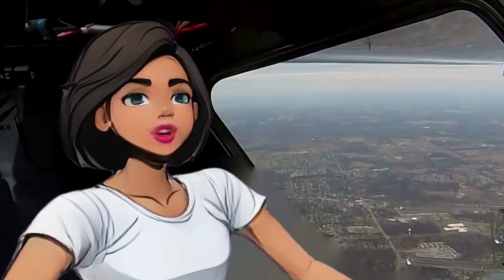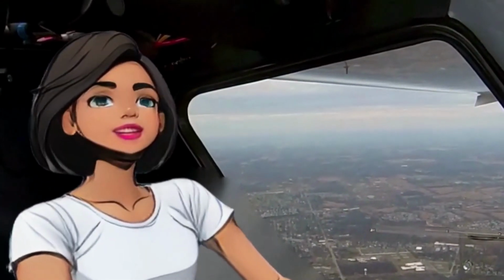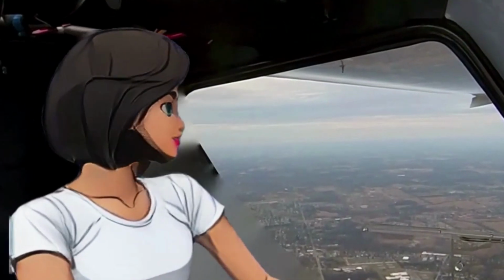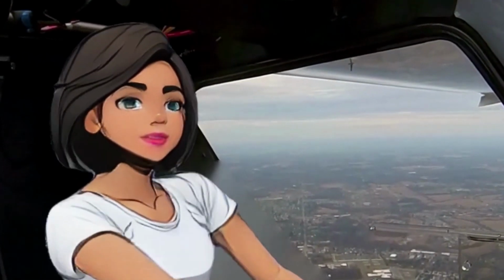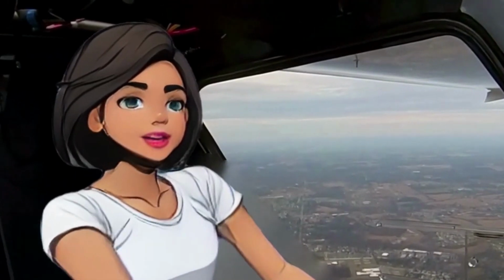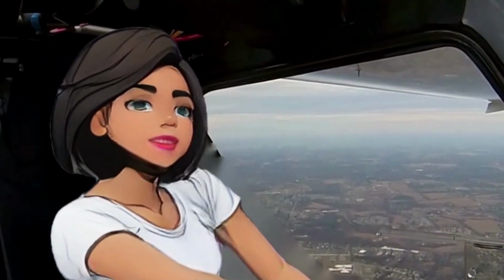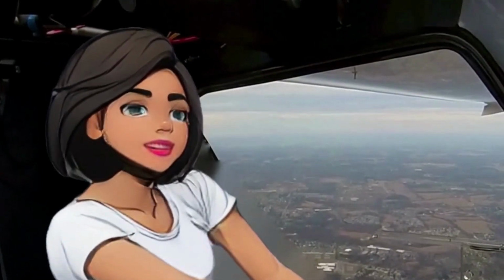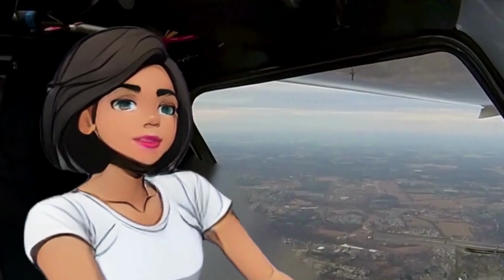Wow. Controlling an airplane is more complicated than I thought it would be. But if we focus on one phase of flight at a time, it is something I think I will be able to master with some practice. First, I need to decide what airplane attitude and power setting will make the airplane do what I want. Then I need to use the elevator, ailerons, and rudder to put the airplane into that attitude.